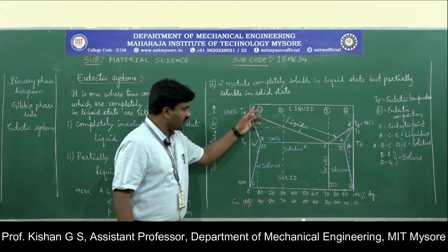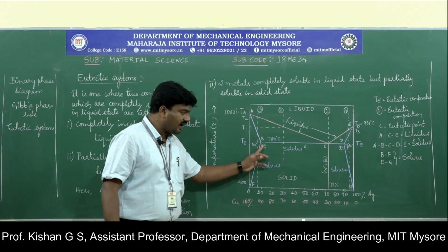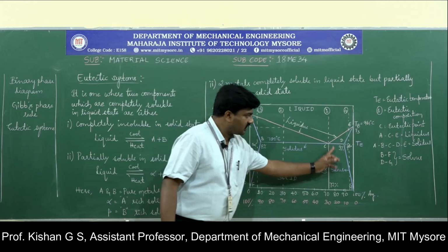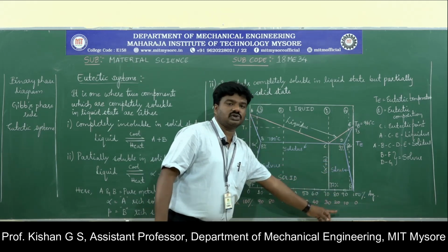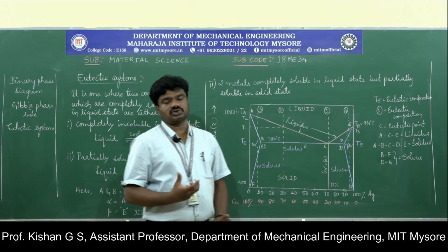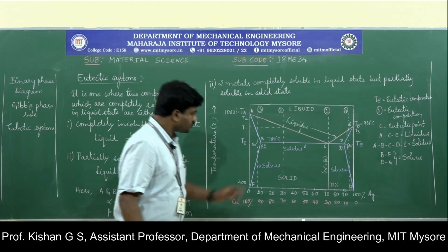So what happens at that particular composition? Around 8% of composition, this 8 is the composition of silver, whereas towards the left 92% is the composition of copper. That is where you are supposed to put your interest, where the partial solubility actually comes into the picture.